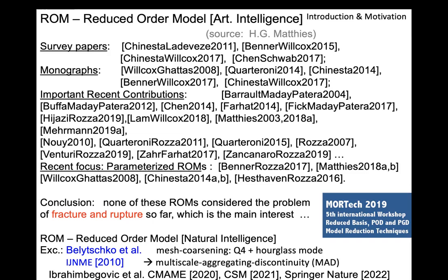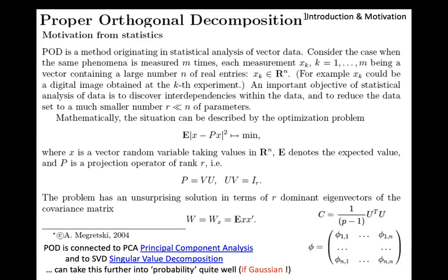You know, this was the idea. So how they build these things, in a nutshell: if you have model superposition, you compute your vibration modes from the stiffness matrix and mass matrix.